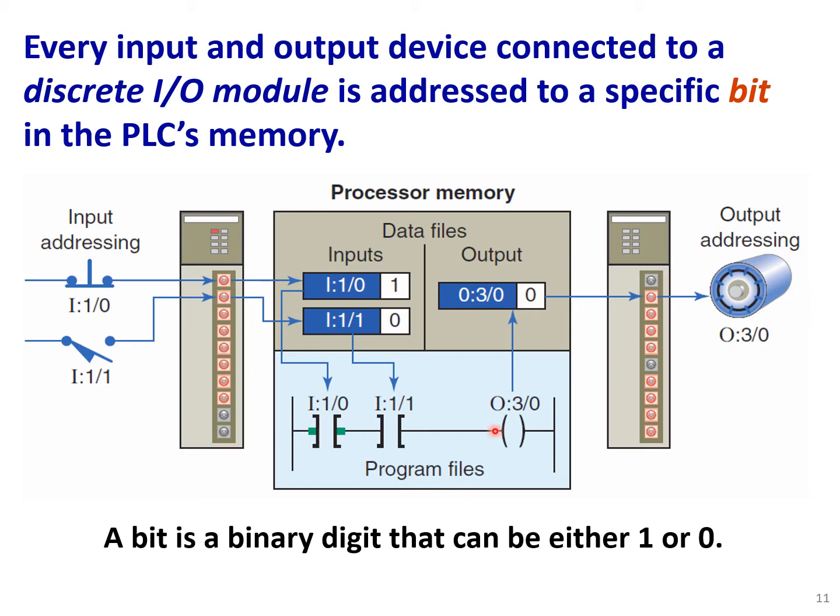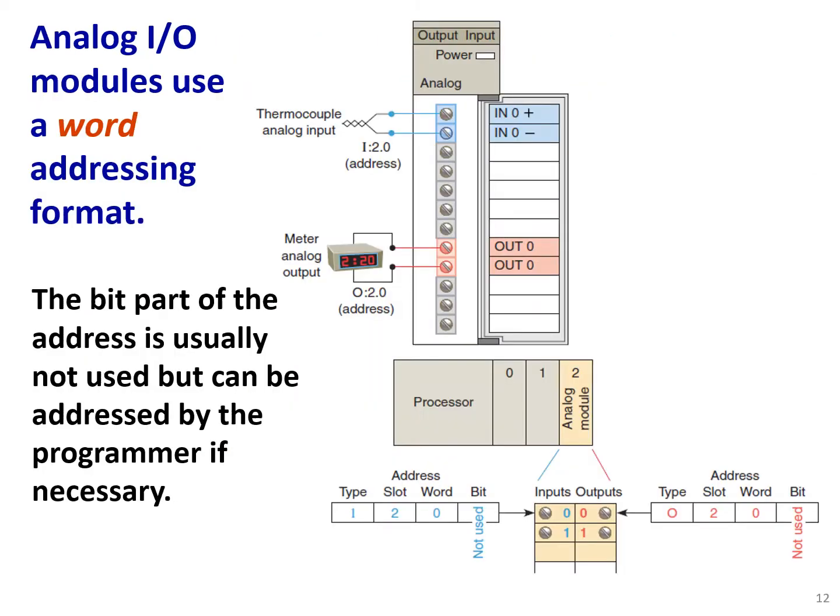At this moment, here is the PLC ladder logic program. As you could see, we have 2 inputs in series and finally a coil or output. So since the logic doesn't hold here, this one is false, and this one is true, then the output is false, or the coil value is 0 and the output is off.